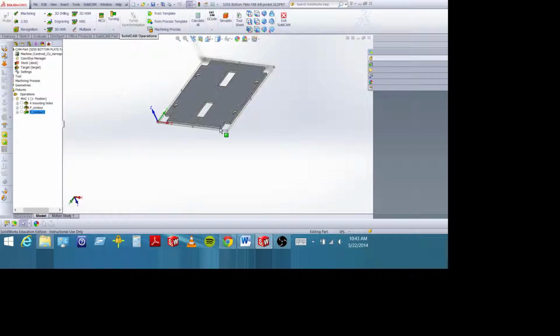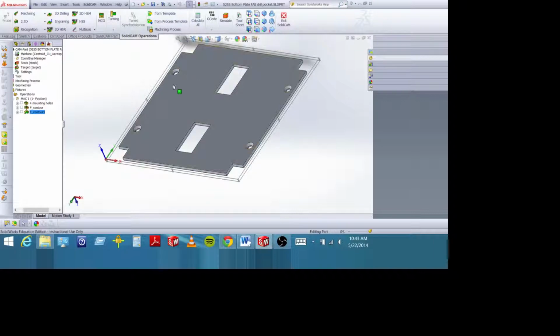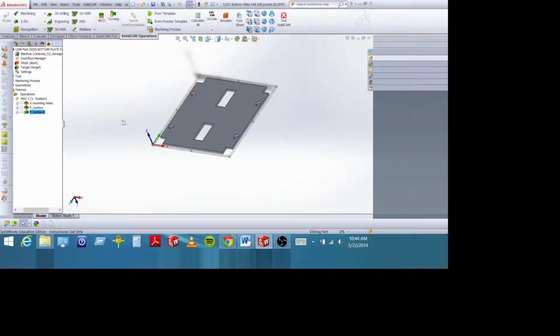I'm going to teach you one interesting method, which we don't use very often, it's kind of rare. If you had a piece that was a little bit bigger than this piece of stock, you could put clamps out here so they're out of the way of the tool running around the outside. And then instead of going all the way through this 0.0787 thick piece of material, you could leave, say, 20 thousandths or so in the bottom. Okay, so if it's 78 thick, you could go like 58. Cut this out, and then you could start stepping down by very small increments.